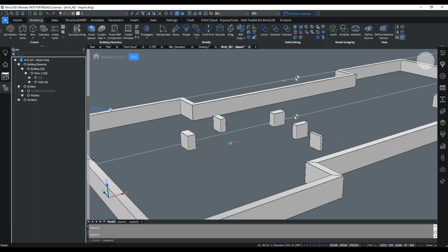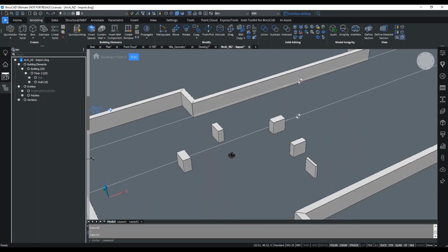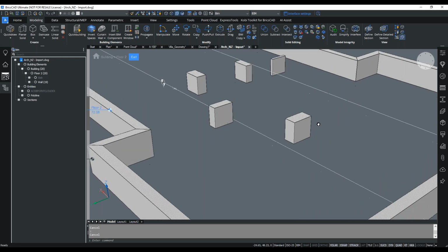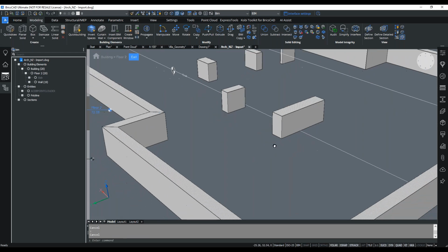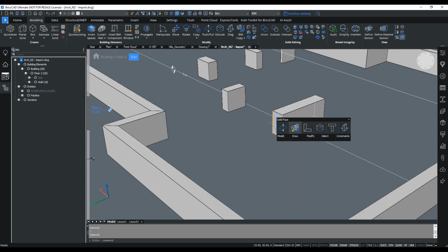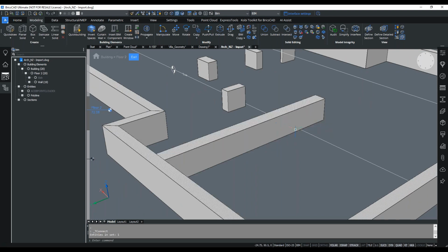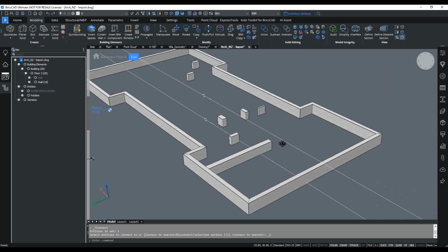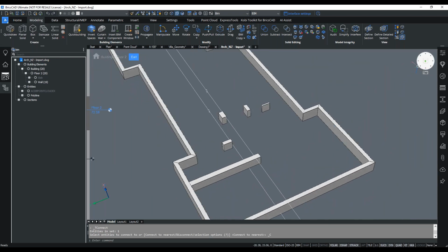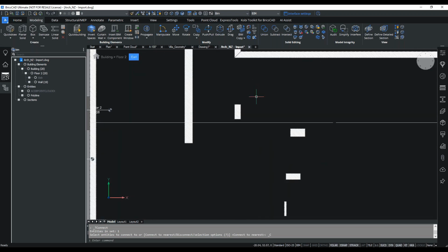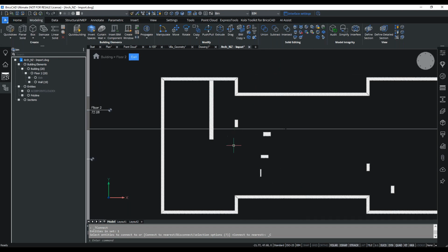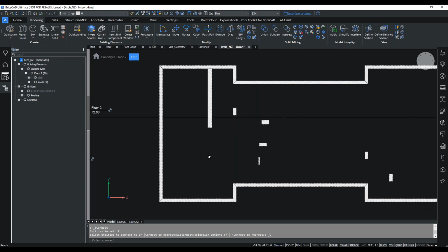So in standard traditional BricsCAD, the way you would now go about this is you would take one of these solids and use various commands to either manually push-pull the walls to specific areas, or click on this command here to extend and connect with the nearest face, which is great, but people have pointed out that they prefer to work on 2D plan views for these. So on the more recent versions of the software, we've got two very relevant commands. We've got BIM trim and BIM extend, and these behave exactly like the standard 2D trim and extend commands.